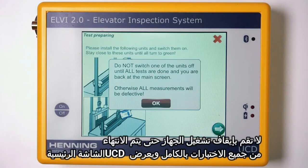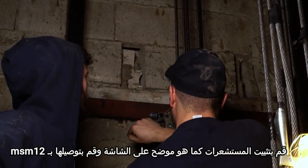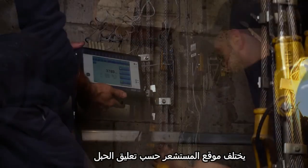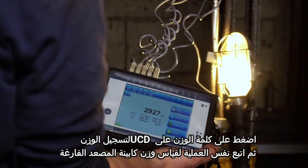Do not turn off equipment until all tests are fully completed and the UCD displays the home screen. Otherwise, all measurements will be irretrievably lost. Next, you'll be prompted to take a measurement of the counterweight. Install the sensors as indicated on the screen and connect them to the MSM12. Sensor location varies depending on rope suspension. Press Weigh on the UCD to record the weight. Then follow the same process to measure the weight of the empty elevator car.